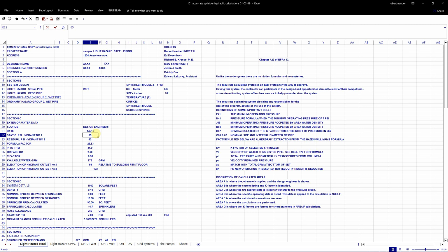Go to the flow hydrant and remove the cap. Install a reducing coupling for the 2.5-inch pitot nipple. Install a pressure gauge on the pitot nipple. This should be an oil-filled pressure gauge to handle any vibration. This arrangement will match the maximum water demand needed for most systems. At the end of the pitot nipple, install a 2.5-inch hose monster to avoid damage to the surface or autos that may cross your stream.